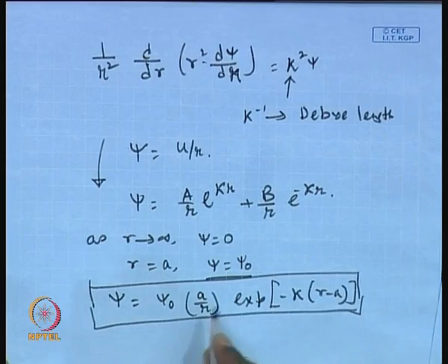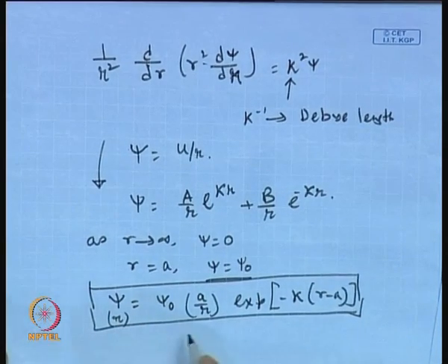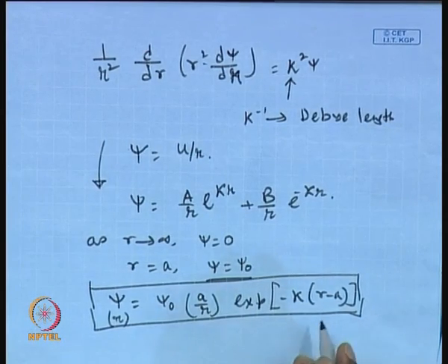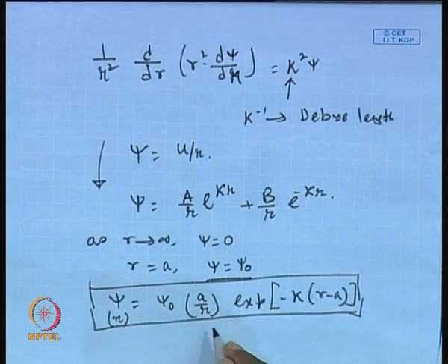So, this gives the potential around a charged sphere as a function of radial position from the center. Now, a is the radius of the particle and r is any radial location. From this point onwards, in the next class, we will calculate the surface potential or zeta potential that one can get in an electrolytic solution, which depends entirely on the electrolyte concentration, nature and things like that. Then we do simple calculations and see how that will influence our filtration performance. Thank you.